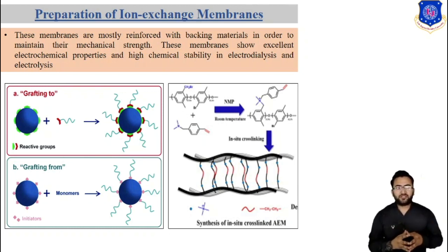Perfluorocarbon cation exchange membrane for the alkali process has an anisotropic structure in the cross section of the membrane. The cathode side of the membrane has a thin carboxylic acid group layer of a given ion exchange capacity, and the anode side of the membrane has a thick sulfonic acid group layer or carboxylic acid group layer of a high ion exchange capacity. So this is about the ion exchange membrane.